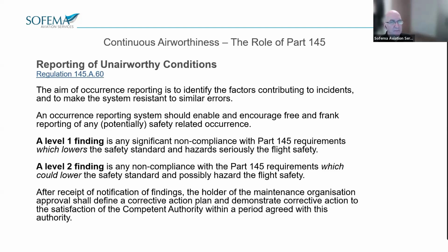So anyway, after receipt of the notification of the findings, the holder of the maintenance organisation approval shall define a corrective action plan and demonstrate corrective action to the satisfaction of the competent authority. And there's a time limit placed on that. Certainly level 1 findings have to be done within a pretty short time limit. They have a very high priority.